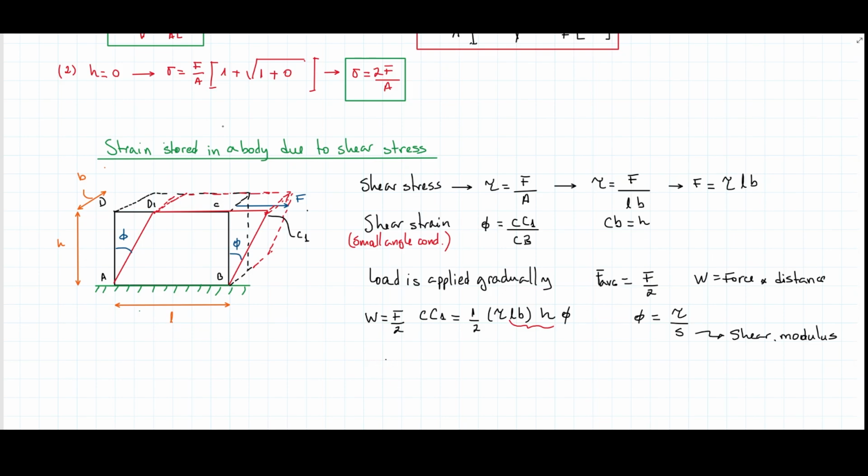Now also considering that, let's call it U, shear stress, equals to what? 1/2 of what? Of shear stress times the volume. But then we have phi here, and this can be related to the shear stress using the shear modulus here. So I can factor this into this equation, and in the end, I'm going to end up with this equation here, S square here. So every load type, like point load, shear force, torque, bending moment, or any other combination, can be used to find out how much is the strain energy stored in the body, in this case.